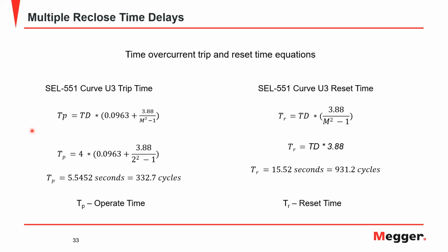Hi, another interesting question, and the answer to this one is do a proper short circuit study, and the tool that you're using can tell you what are the proper coordination times that you have to use for both. Fortunately, today, microprocessor relays can be coordinated whether downstream or upstream with other microprocessor relays and with electromechanical relays.